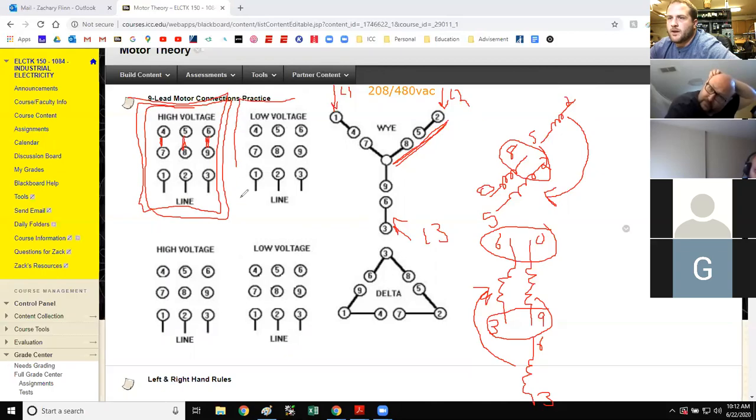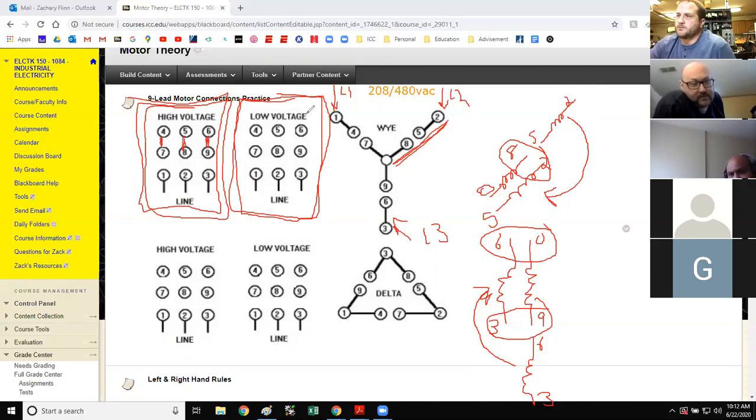So on the nameplate, you're going to see something like this. So what are the connections then? I just showed you 2 of them. Right here is one. Right here's another one. Yeah, you connect the dots, right? So 4, 5, and 6 would be one line. 7, 1 would be one line. 8, 2 would be one line. 9 and 3 would be one line. Very good. Okay.